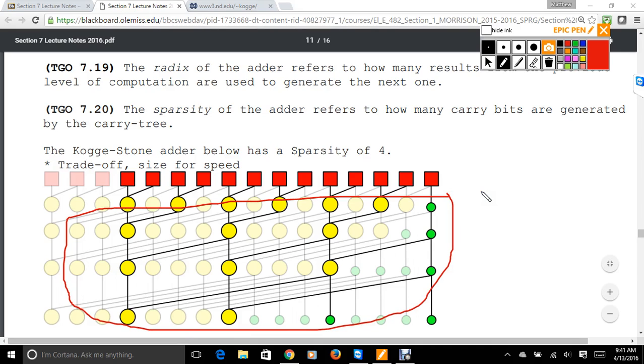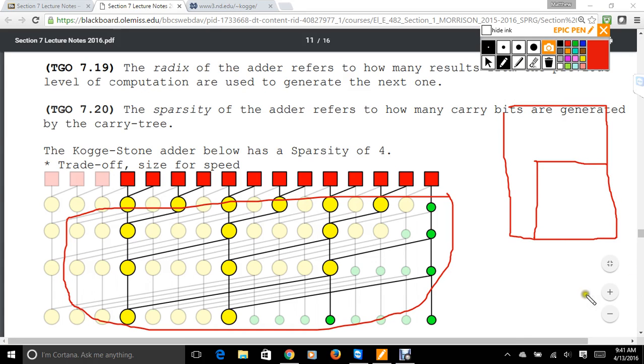Does that make sense? And from a CMOS side, well, that goes good because instead of having it this big, we're now cutting it down to probably about that size. So less area, runs faster, reduced power consumption compared to the full Kogge-Stone adder. But then again, if you're getting down to your normal full adder, it's probably about that size, but it runs a lot slower. So this is where good design requires good compromise comes into play.